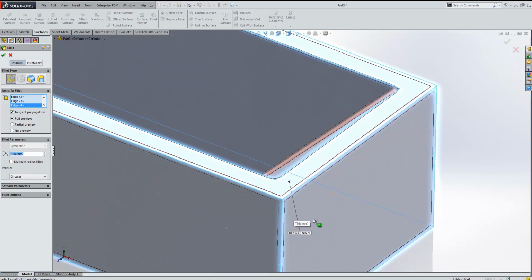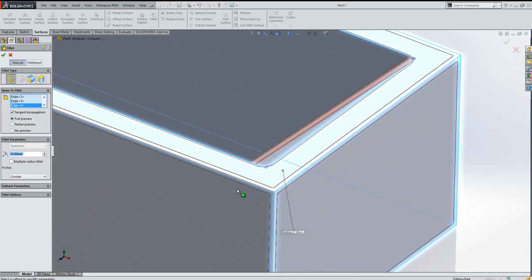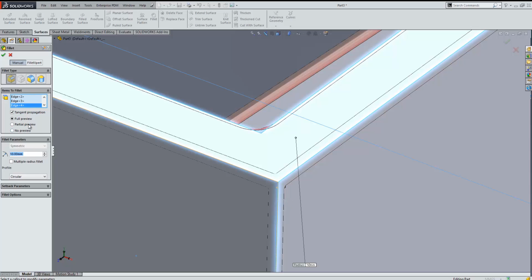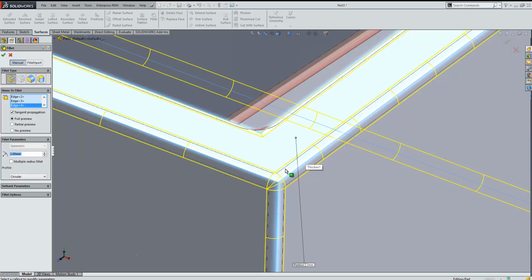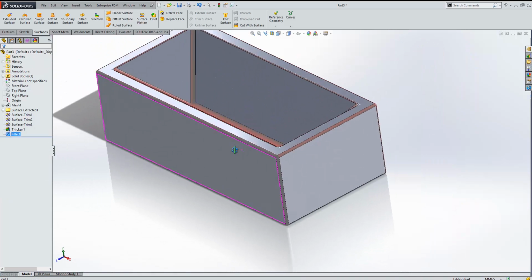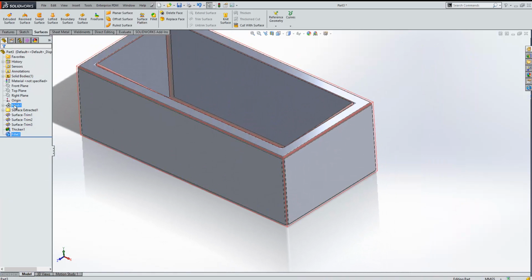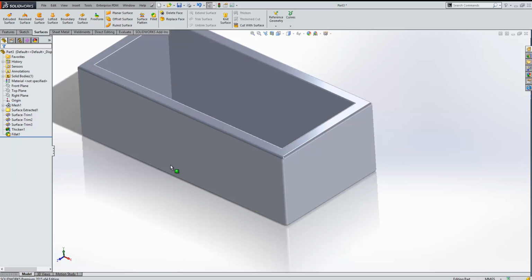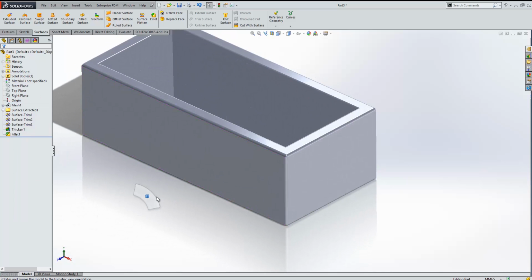And then all we're doing now is looking to do a radius on those, and in this case I happen to know that it's 2 mil, and we can see that that lines up with the remaining fillet faces, which don't usually get removed by creating our surface bodies. And if we hide the mesh, you can see we're now back to our solid house brick.